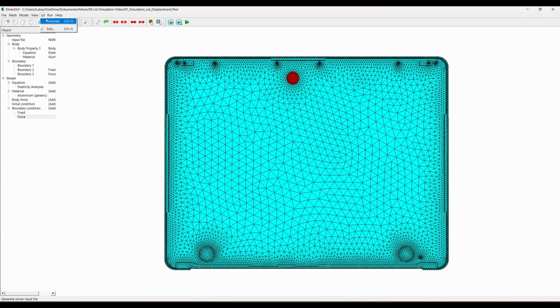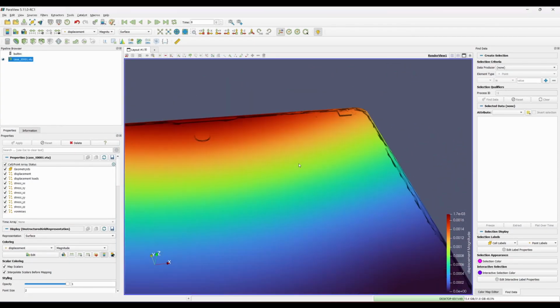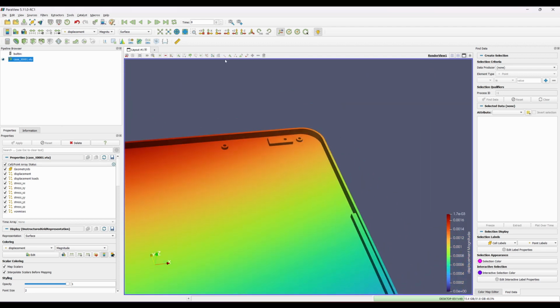Knowing the surface area of my boundary condition with around 143 mm squared, I need to apply a pressure of roughly 77,000 Pascal to generate a force equivalent to that of a 1.1 kilogram weight. Okay, after running the simulation with these updated values, we get a displacement value of about 1.29 mm on the corners of the 3D model.